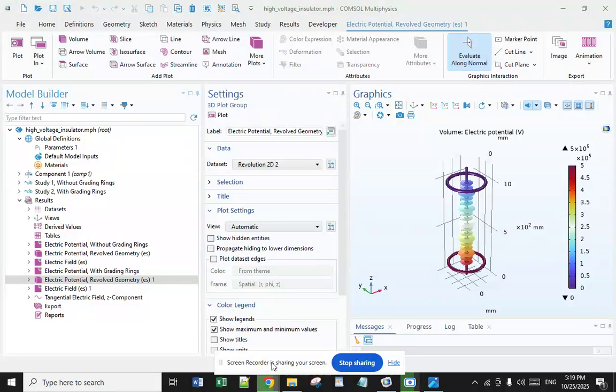Insulators in industry. Specific applications in different sectors. Electrical sector. Insulators are essential in the electrical sector as they enable the safe and efficient transmission of electrical energy. Insulators are used in transmission towers, poles, or transformers and are made of different materials such as glass, porcelain, ceramic, and polymers.